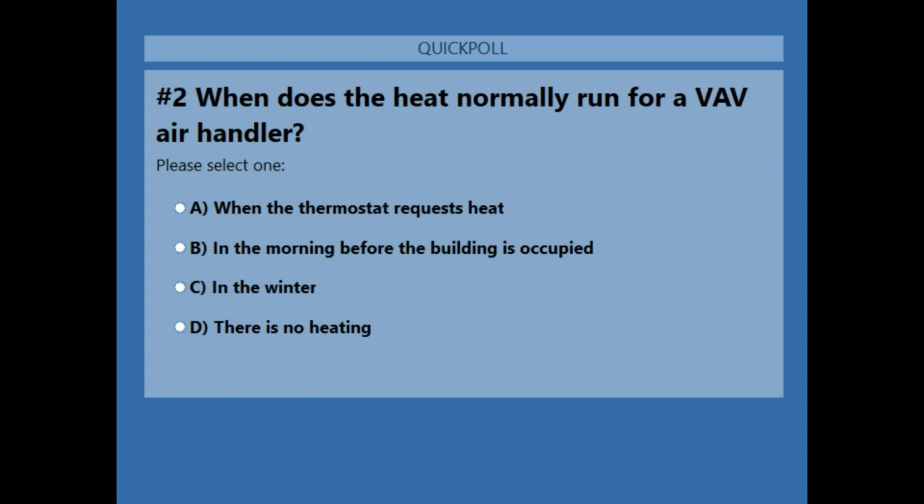The other time you may do it is if you have existing ductwork. Maybe I have an interior zone that has 4 duct runs coming off the main branch going to it. Or maybe I have a conference room that has 2 duct runs coming off the main branch to it. It may, in some cases, depending on how accessible the ductwork is, be easier to put 2 dampers in with one thermostat than it is to redo the ductwork to have only one larger branch run running to that zone. So normally 1-to-1, but you can do it a little bit different.